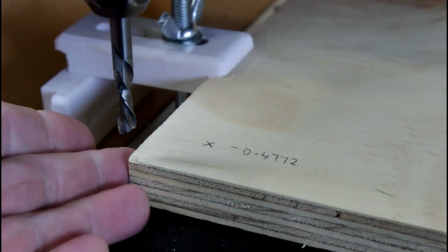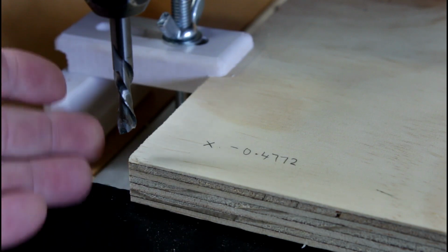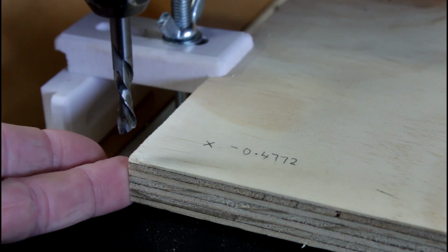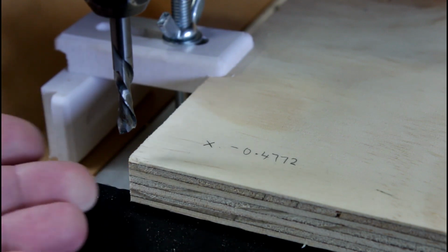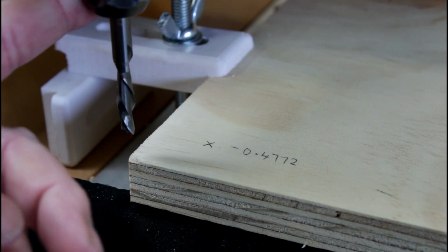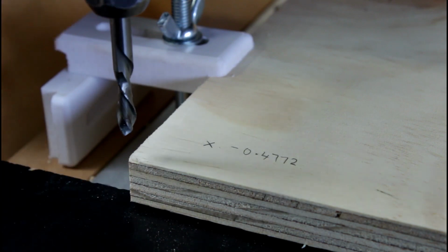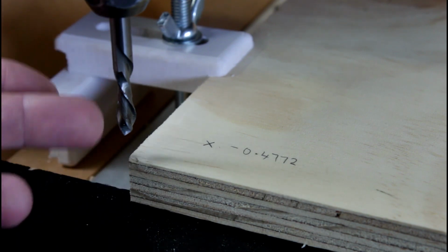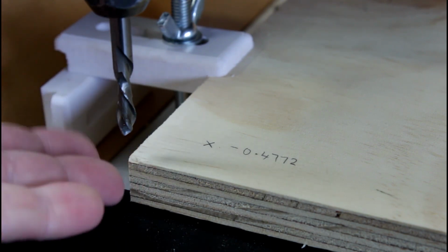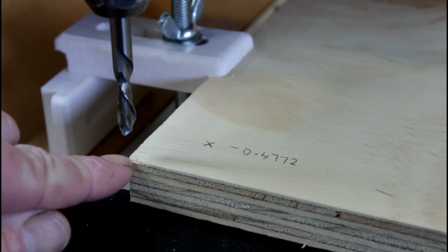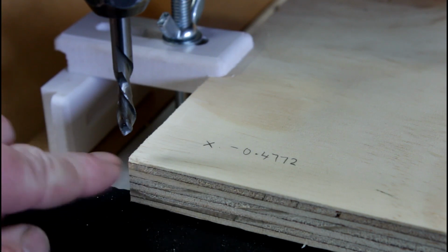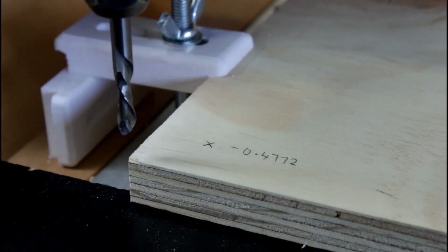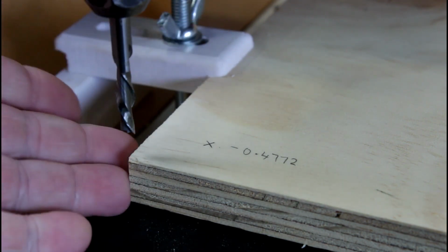Okay. On a job like this, I like to have a couple of reference points, just in case I end up with a power cut or something like this, and the job is savable if I can reset everything back to a set reference point. Now, obviously, resetting my X and Y value to this corner here is going to be quite difficult because I haven't really got anything to line it up with. The initial setting isn't absolutely critical, but if I had to reset it, it has to be perfect.